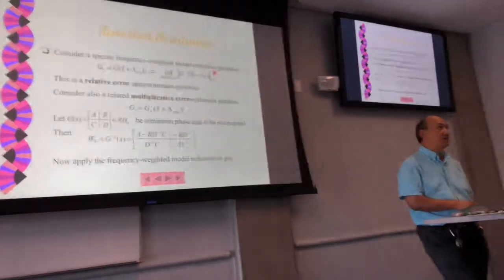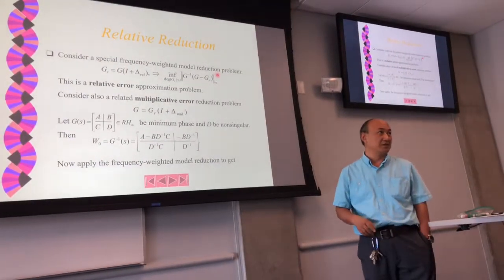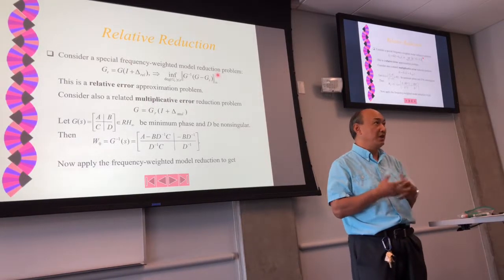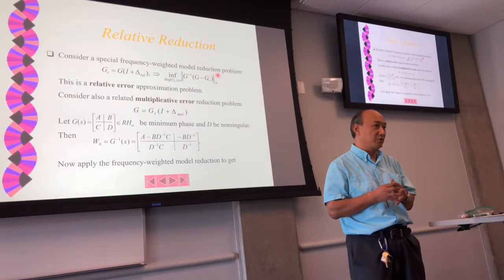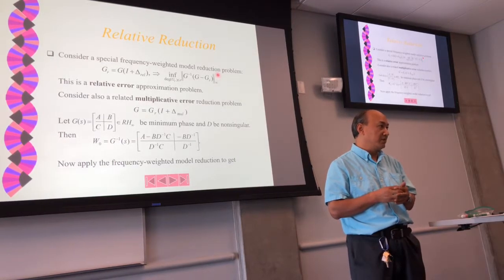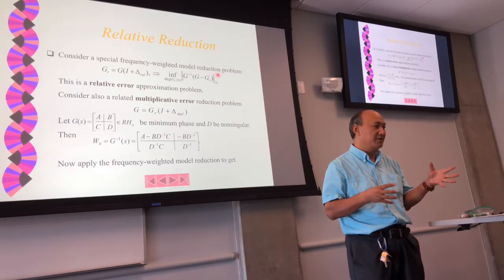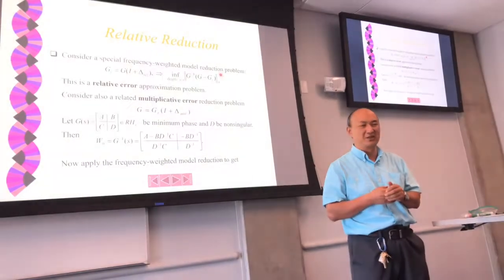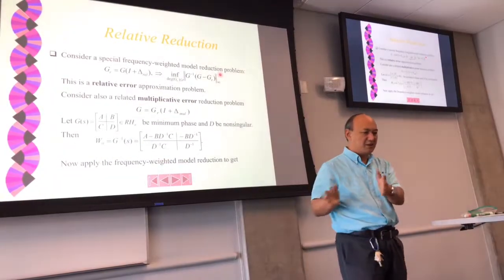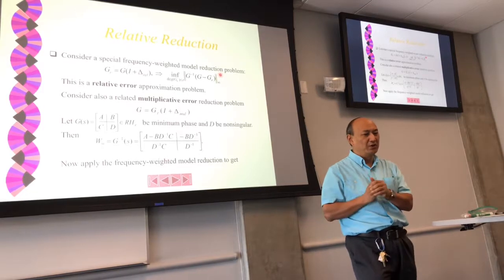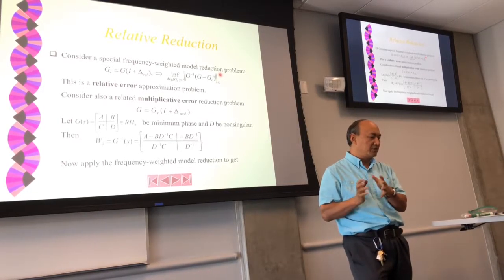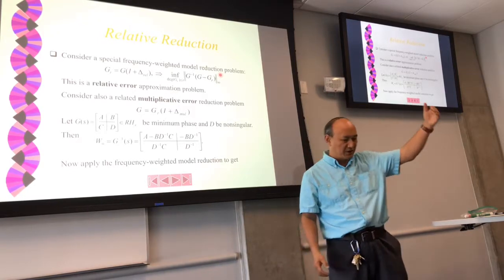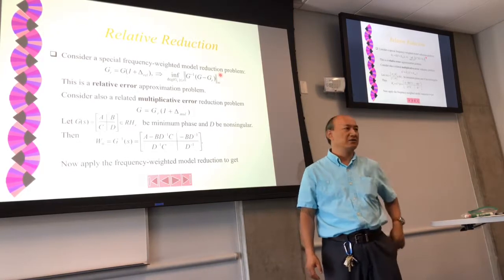And again, balanced model reduction turns out to be a fundamental technique you should have in robust and optimal control. Because when your system is too complicated, you should say, let me try balanced reduction and truncate those small Hankel singular values. Another good habit is, given a system, you should check all the Hankel singular values.